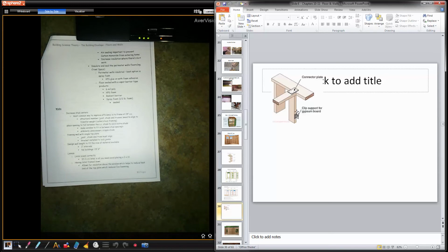It's not a bad thing. Float in the corner. So this sheet of drywall on this wall would be screwed in regularly. This sheet would have been the first one to go in, so that goes on first to hit that bracket. That goes in second, gets screwed in regularly. And then whenever you tape the seam with mud and paper tape, it'll hold the two sheets together. So this sheet that's not screwed will then follow this sheet. So if there's any movement on this wall for some reason, it'll follow that wall, reducing cracks.